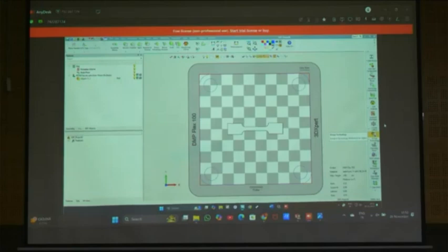As I am moving here, less contact, less contact. The very starting position should have less contact actually. Suppose if it is like this, your entire surface is in contact. When the roller is moving like this, the first part touching the build plate has a very high contact area. So the build can fail. So what they suggest is to rotate the body by 5 or 10 degrees so that the contact can reduce. That is the recommendation actually.